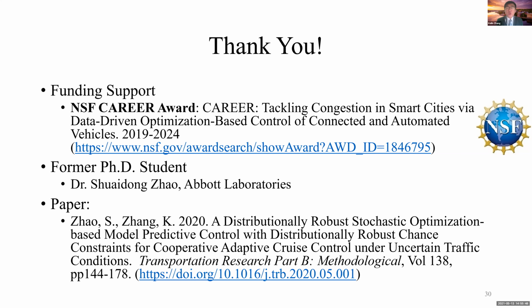Especially, we also use the real-time optimization nature, because for every 0.1 time step you have new data in and you calculate the optimization problem. The whole idea here is that we use a warm start method. So you don't need to calculate this optimization from scratch. You can use the previous solution as the initial solution, and then you calculate.